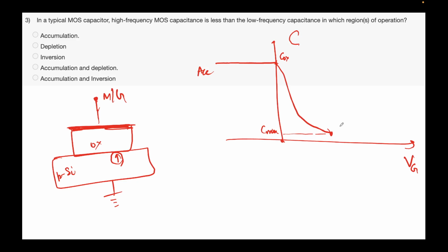Since the electronic energies are different, when you bring these together, so till now they're not touching, the metal, this gray is your oxide, and this band diagram is for the semiconductor. When you touch them together, you can clearly see the EF has to remain the same when you're not applying any bias, but you will see something like this. Even when Vg equal to 0, which means equilibrium, EF is flat. That's the definition of equilibrium, but you can still see some band bending.